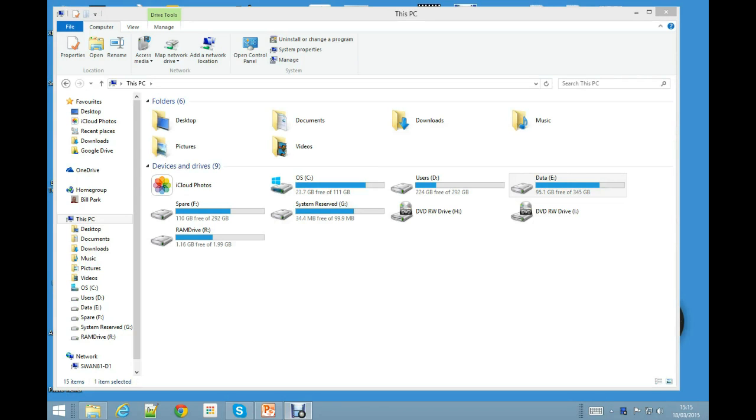So now we'll have a look at the eTrex Legend. This has a mini USB connection on the back, but it's a fairly old device, so it may not be mass storage, it possibly would be serial protocol. And the way to find out is just to connect it up and wait and see what happens.